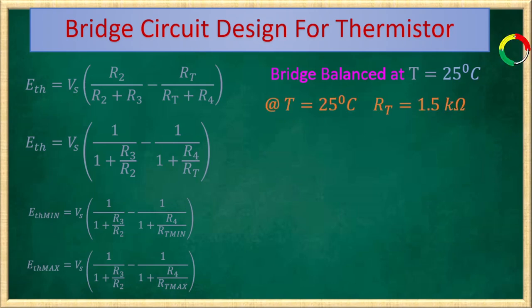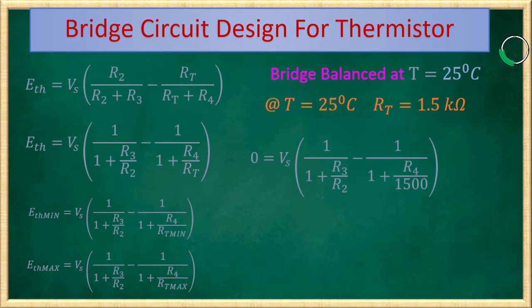What it means is that the bridge gives ETH equals 0 at 25 degrees centigrade. Our thermistor gives RT equals 1.5 kilo ohm. This is from the datasheet. Now, equating our ETH equals 0 at this resistance value, we get by rearranging R4 = 1.5 kilo ohm times R3/R2.